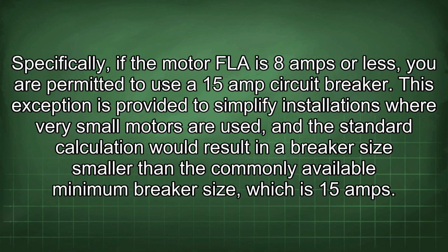Specifically, if the motor FLA is 8 amps or less, you are permitted to use a 15 amp circuit breaker. This exception is provided to simplify installations where very small motors are used, and the standard calculation would result in a breaker size smaller than the commonly available minimum breaker size, which is 15 amps.